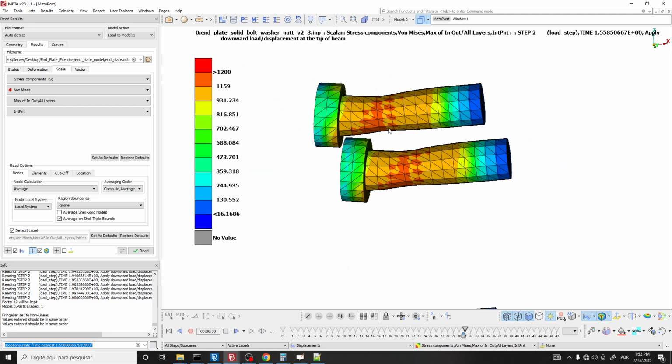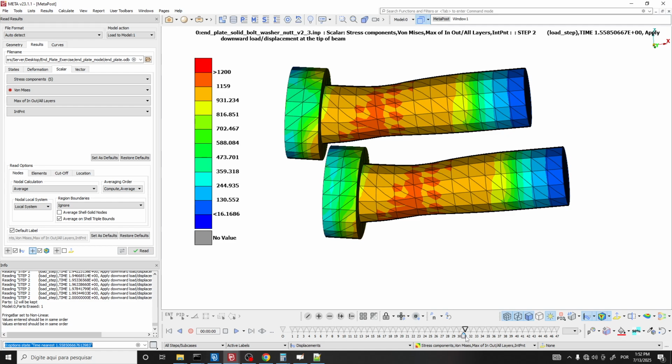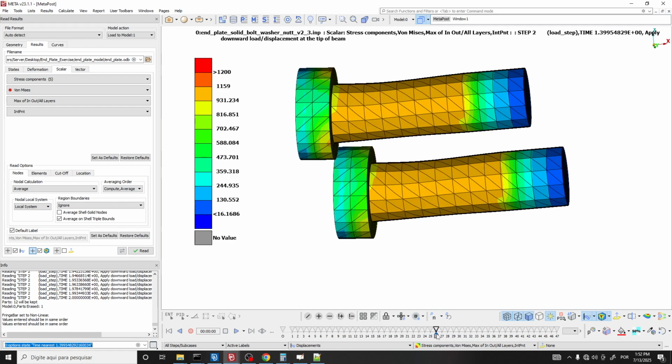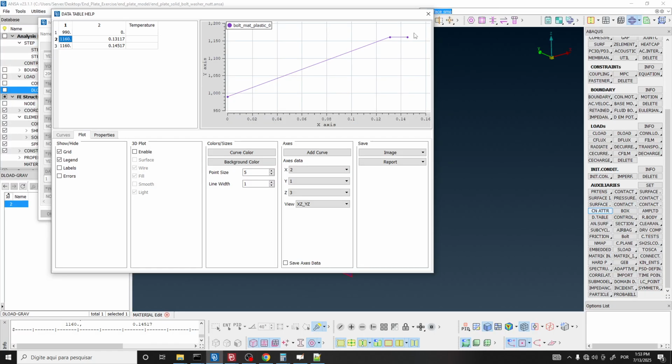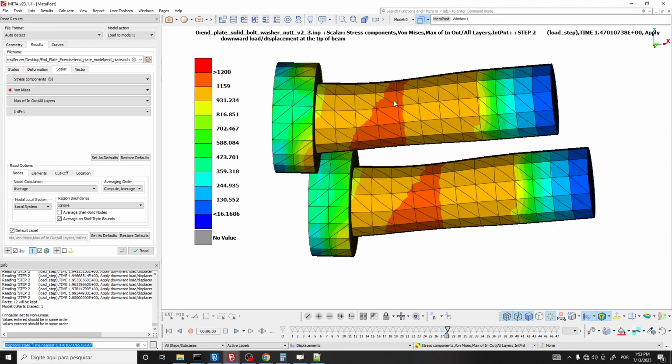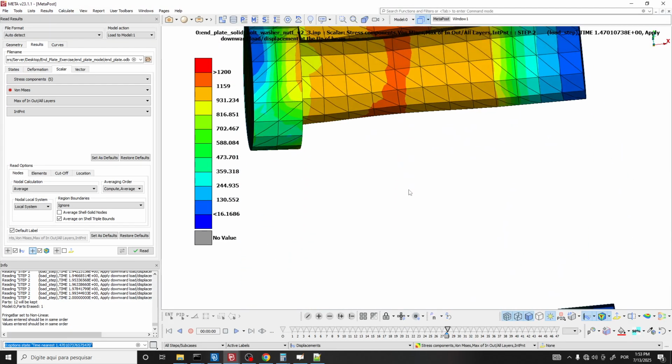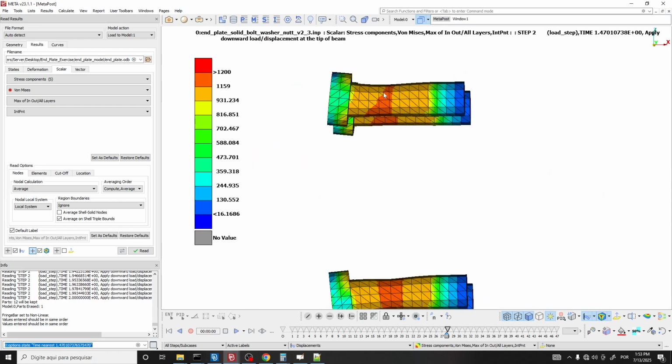Okay, there is one way to insert a damage model here to actually have element deletion, but in this case, the author has represented the bolt separation when we have the whole section in this region here. So we have lost all the stiffness of this bolt for this whole section. Okay.